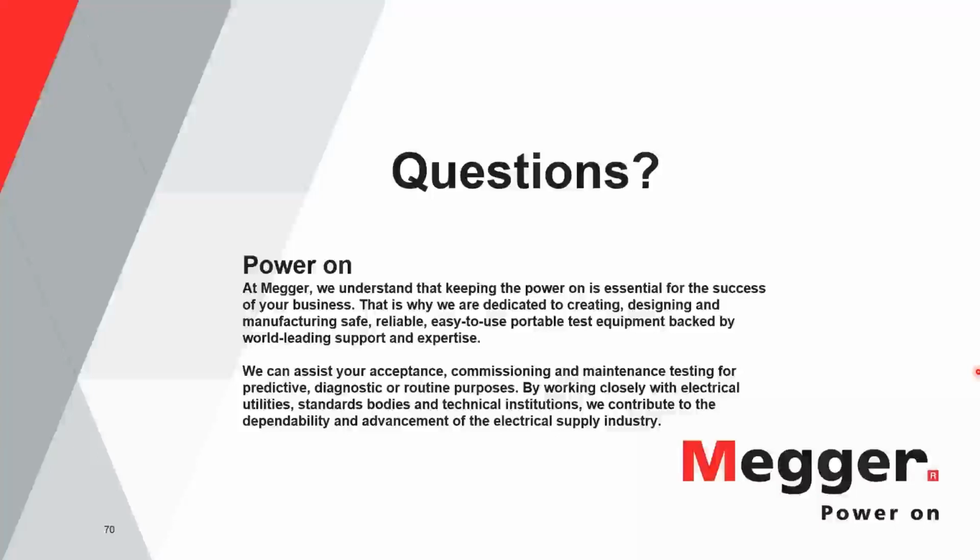So I would say with a smaller transformer, just testing time, you can get done in like 45 minutes, and then maybe double that as you start to get higher up and you need a man lift to move around the transformer to make your connections.